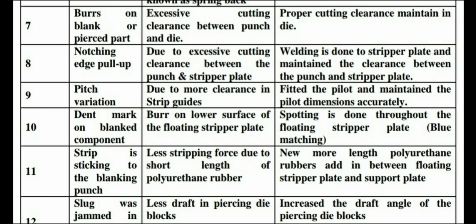Then pitch variation. So due to more clearance in strip guides, this is a cause for pitch variation, and the remedy is fit the pilot and maintain the pilot dimension accurately. So you can do this. Then dent mark on blanked component. So burr on lower surface of the floating stripper plate causes this dent mark on blank.